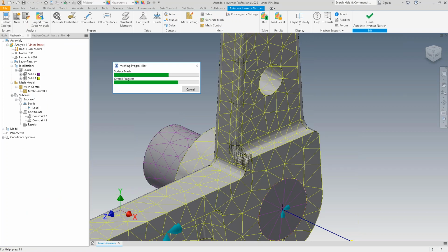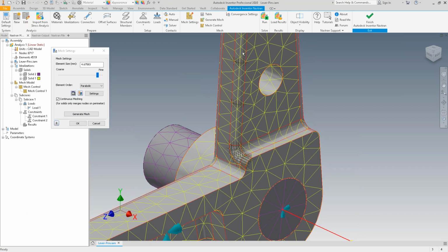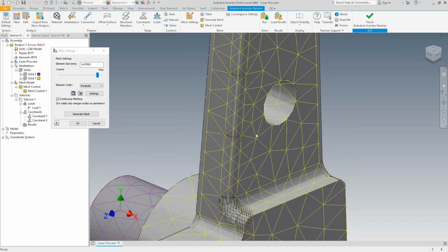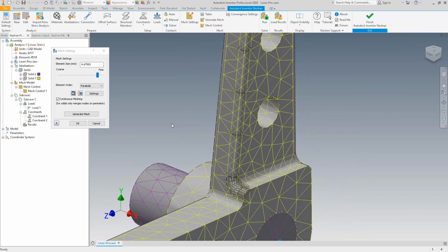Now what you're going to see is the mesh is going to change slightly. We did get refinement on those faces. The mesh elements of those faces got smaller, and in any of the connecting faces, it evenly distributes that mesh size change through those faces. So it did refine them. We're getting a much smaller mesh in here, and that's a benefit. That can help us focus in on an area that might be having some stress. For that matter, the stress could move because we're working with a finer mesh, we're working with more detail. It could relocate the stress area or the center of the stress.